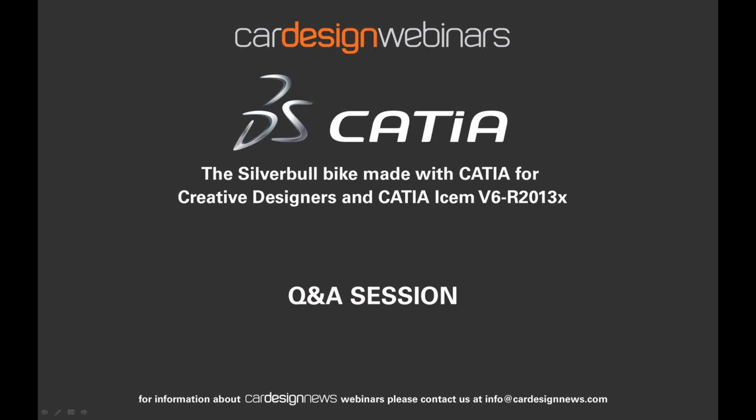With CATIA Icem, what we want to provide is to continue to provide the quality and the precision of modeling of control points, but also to add feature-based associativity, which is called the feature modeling. When you manipulate a control point on the surface, you are able to change the surface with all the precision, while keeping the continuity with all the surrounding surfaces.